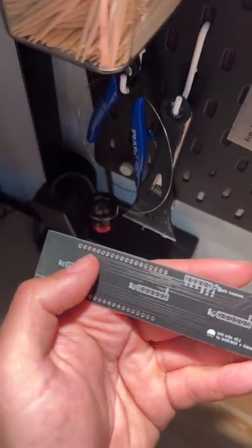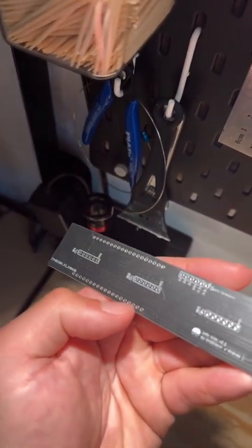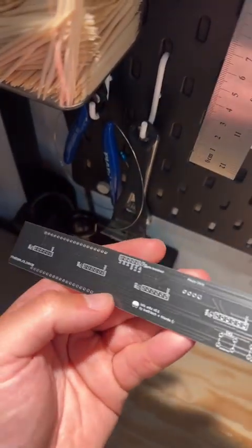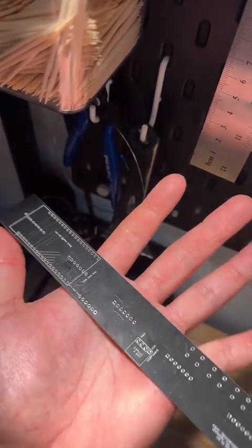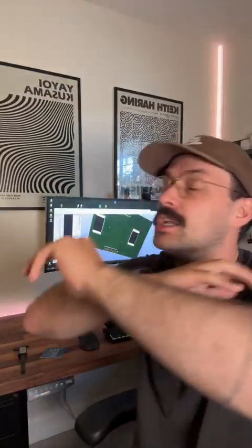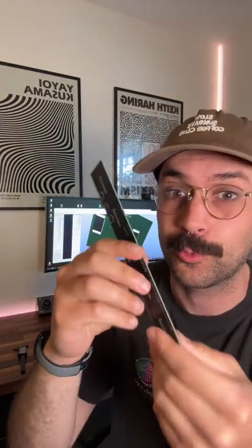They don't look like big holes. You can see these little dots here where the PCB is terminated. Those are all vias that allow me to jump over all these traces and run them across the back of the board. Now, this rabbit hole goes a lot deeper, but understanding the basic idea of vias and different layers of the PCB is going to unlock so many different things for you and allow you to make really compact boards.